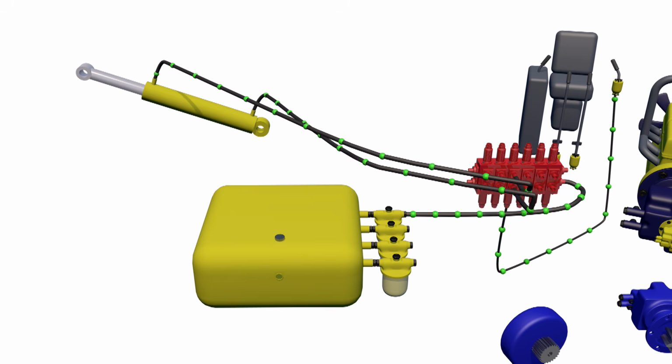The expelled oil is directed through the circuit that has opened in the hydraulic distributor into the hydraulic reservoir, passing through a filter. If the control lever is returned to the neutral position, the high-pressure flow will cease, and the piston in the cylinder will stop and be held in that position. To move the cylinder piston in the opposite direction, the control lever must be moved to the opposite side. The oil will now flow through a different circuit, but according to the same principle. The cylinder piston will move in the opposite direction.